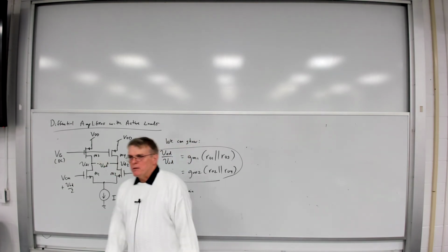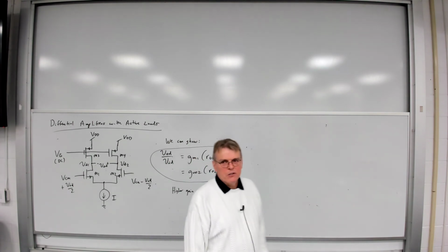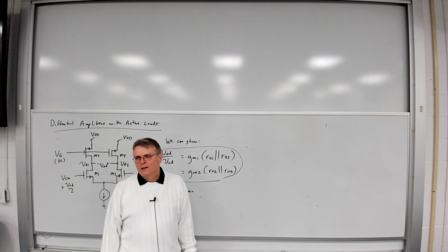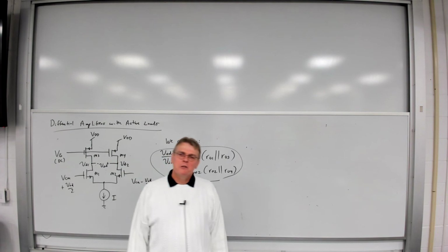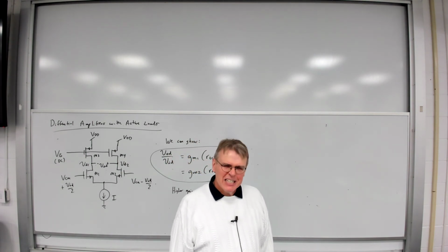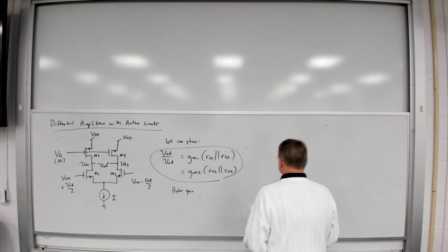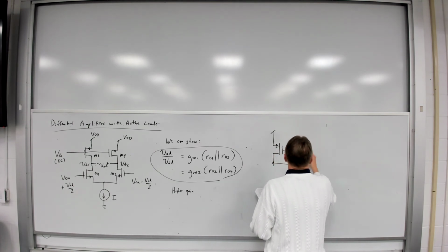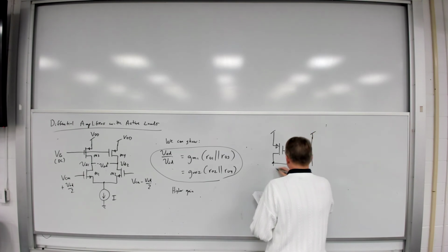But there's another trick we can do with this. If I've got these two transistors, it turns out I don't need an external DC bias. There's another trick. I've got two PFETs. What can I do to those two PFETs? Let's connect them as a current mirror. Let's draw this circuit instead. We're going to let those two transistors, in effect, bias themselves via a current mirror.